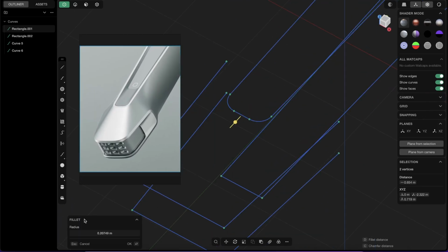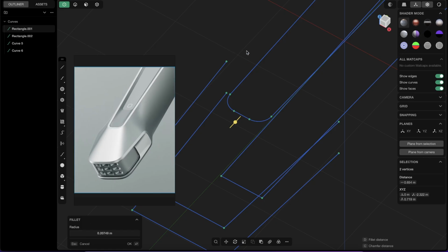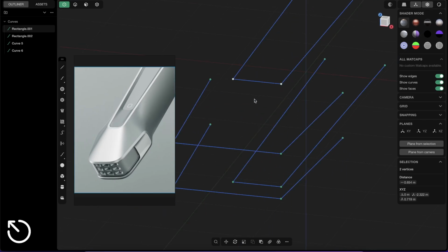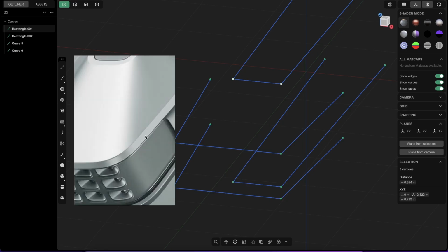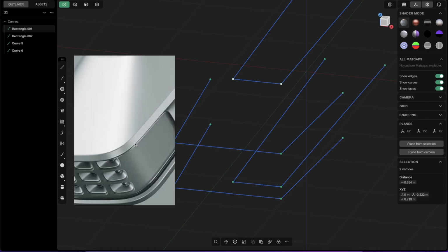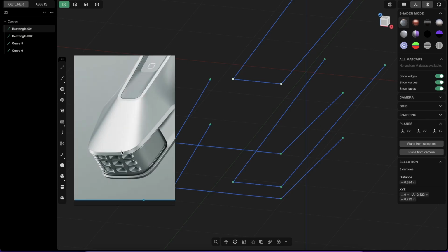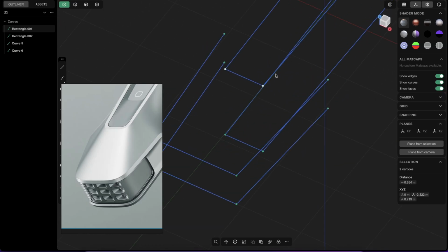But also when we just fillet, we don't have an option for G2. So we have to press escape, and we have to give here G2 and here G2. Also, once you are a little bit more into Plasticity and you have more practice, you just see that this fillet is very, very smooth, and that the fillet just doesn't start from this point on, but rather it takes a little bit of this curvature. So it's 100% G2 or even G3. So yeah, we will do G2.